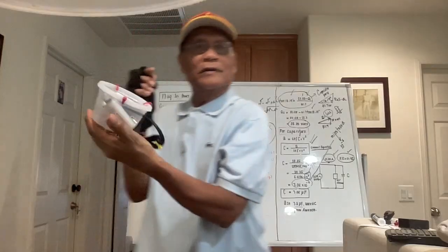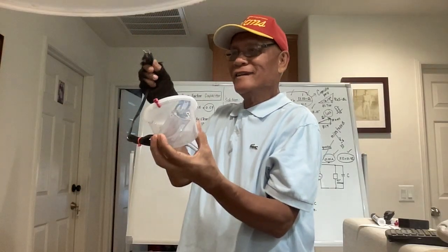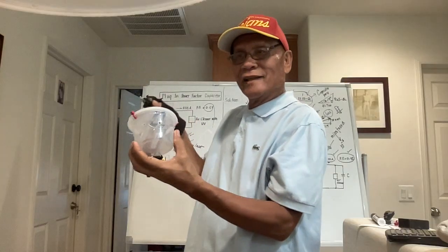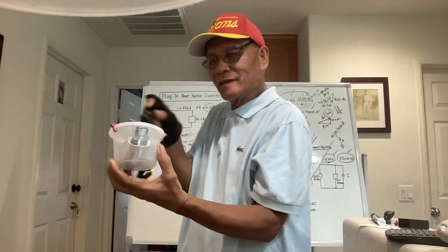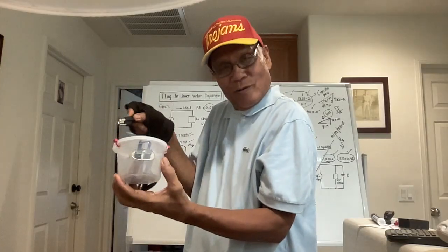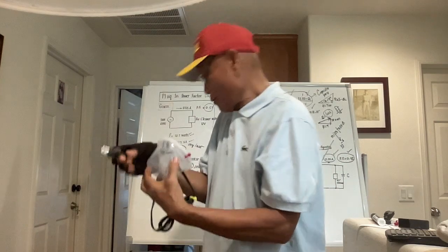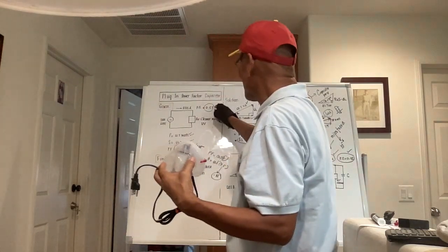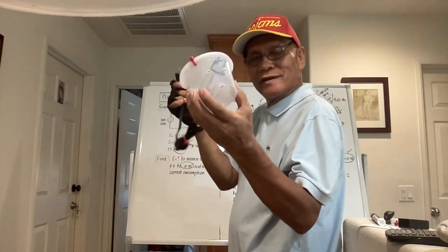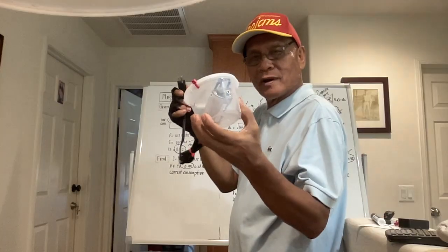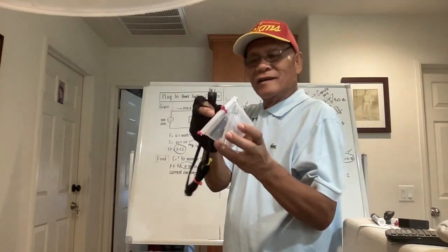This is the capacitor. Okay, this is the plug. So on the air cleaner that I'm using, I will plug in this one beside the outlet in which that air cleaner is operating. And I could improve the power factor from 0.62 to 0.95. And the value of this one is 7.5 microfarad, 400 volts AC. So this is safe inside. This is safe.